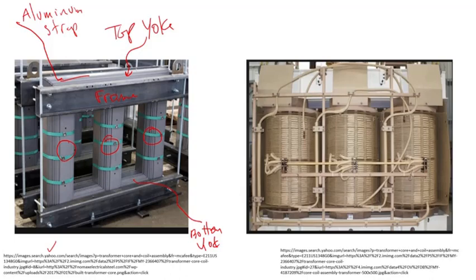That's the best practice. For smaller transformers like pad mount, pole mount, what you see in distribution systems, it might be grounded internally. But if you want to test the core ground insulation, as I'll talk about later, or even power factor, there are certain tests you cannot do unless you remove that.